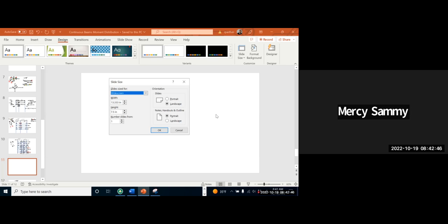So if you're doing the cross, the one that's on the fixed end just becomes 0. But if you're in the middle, if you're taking the one on the left to the right, and the ratio is 1/3, you have to take 1/3 of it. If it's half, you take half of it when you're taking it to the opposite, diagonal side. You follow the ratio on the top, but if it's on the very fixed side, it just becomes 0. Okay.